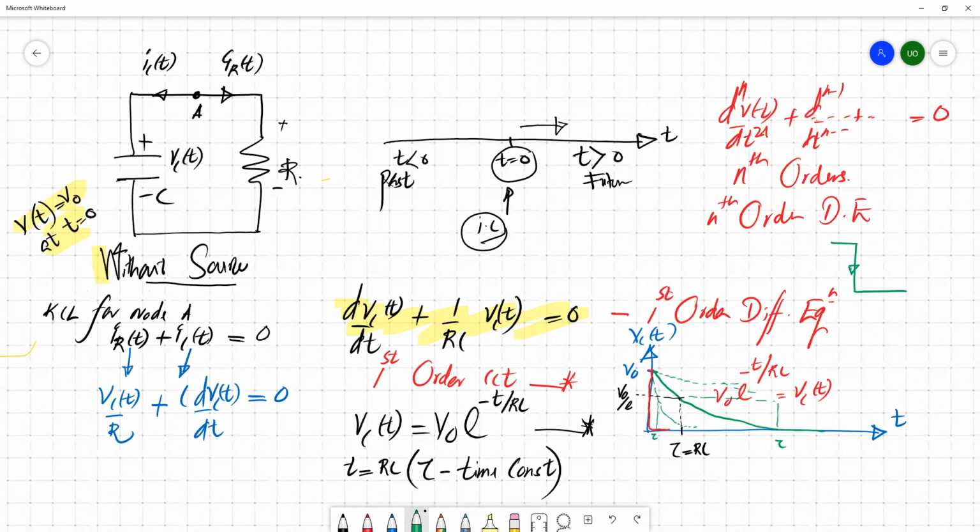We can add another piece of information: during 5 times tau, the capacitor can charge to maximum or discharge to minimum. For example, in an RC circuit, once you plug in an external source, the capacitor gets charged up to a certain value.